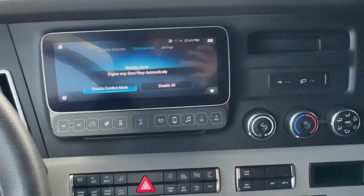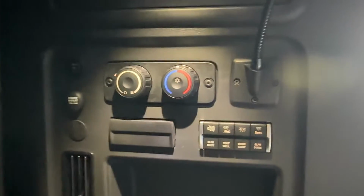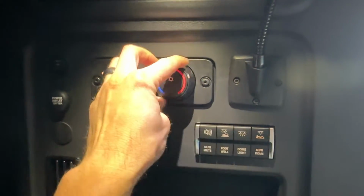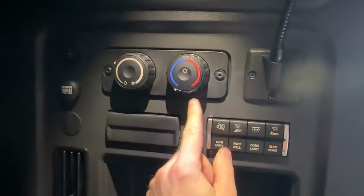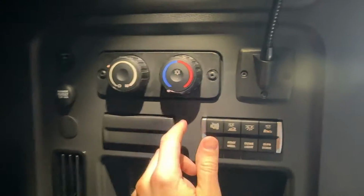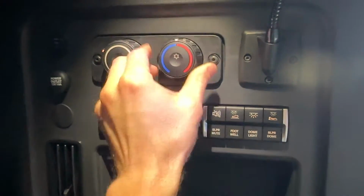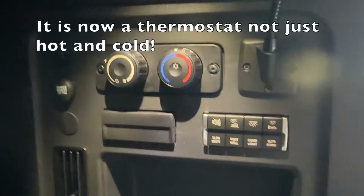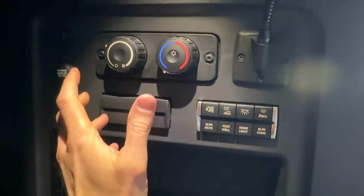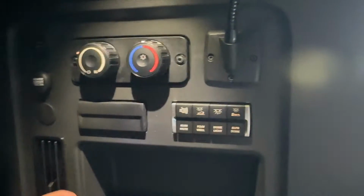So now that that's on, you're going to come into your sleeper. Now you're going to use these controls. The thing to know is it's not just cold and hot anymore. This becomes like a thermostat. It means when you put it here, the truck's going to try and hit 60 degrees. If you put it here, it's going to try and hit 85 degrees. If you put it here, 72 degrees and everything in between. So I always tell people, start here. If you want it super cold in the truck, don't crank it down here. Just leave it here. It's a thermostat like your house, so it'll use cold air to cool you down.